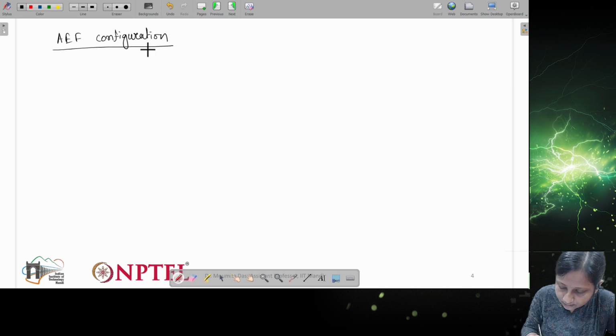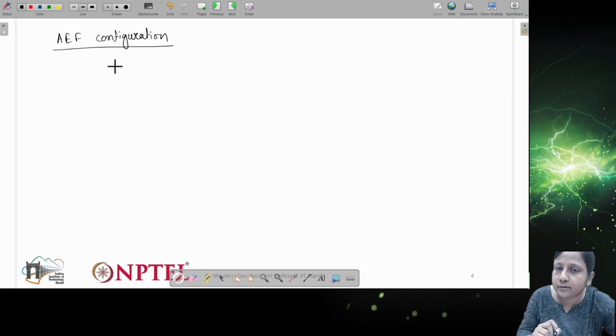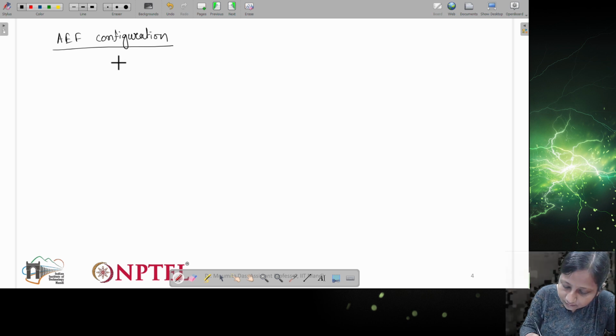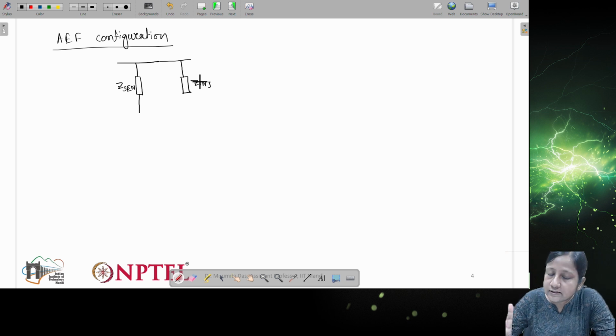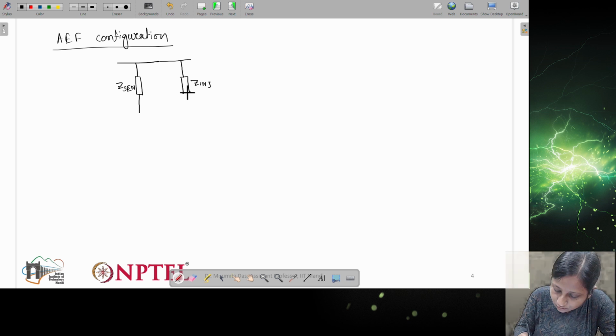If I draw this, generally what happens if I try to expand that capacitor, basically the arm where G output multiplied by Z injection is shown, it will have one sensing impedance. So I can represent Z SEN, the sensing impedance, which will be connected to Z injection impedance. This impedance is with respect to the injection of the noise signal. So this is what I have also shown.